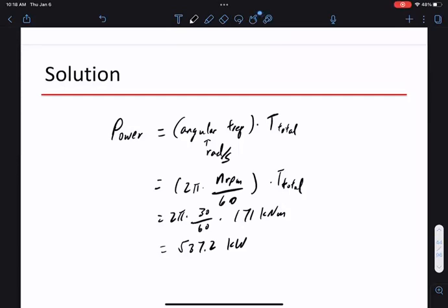It gives you mechanical balance. The weight for different configurations is all evenly distributed. Right, so the exact same calculation for 3-phase power will tell you this. The sinusoidal shapes, you add the sinusoids, they all cancel. So the weight is very evenly distributed. So 3 is nice, better than 2. 3 gives you a good number of blades and reduces the turbulence. Okay, so it's a good trade-off. It seems like this design will be fairly robust. 3-blade turbines. Any other questions for this?